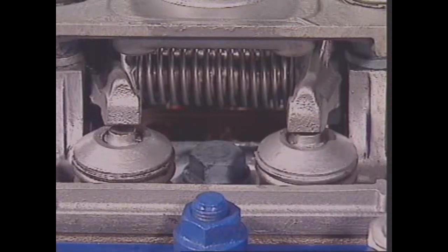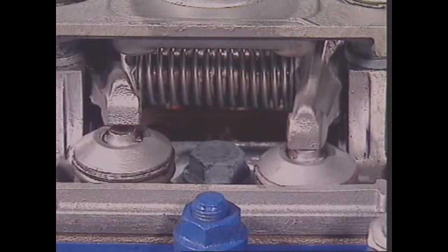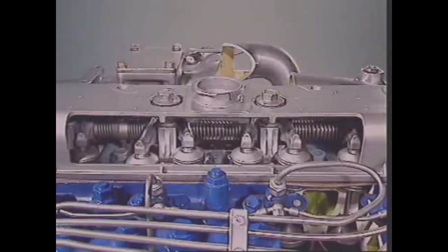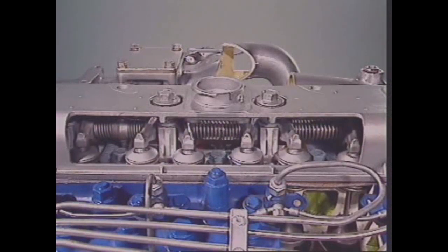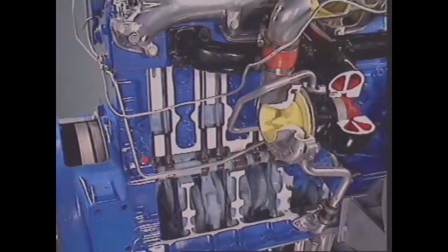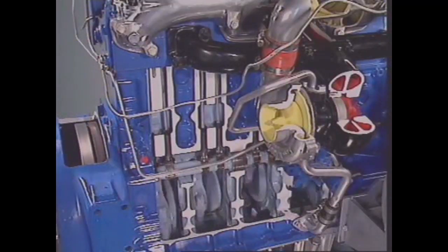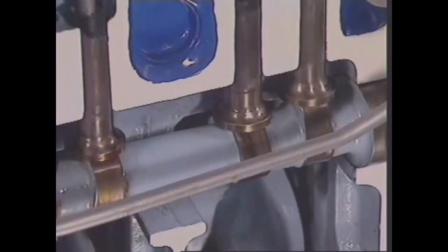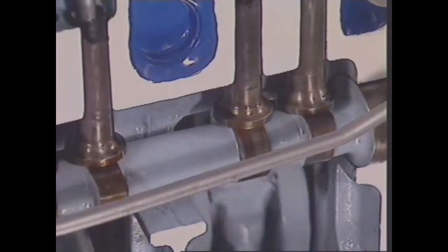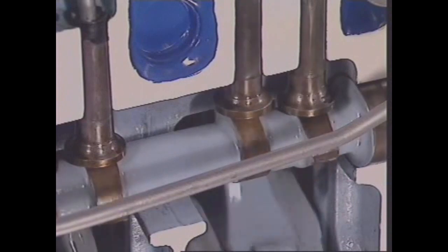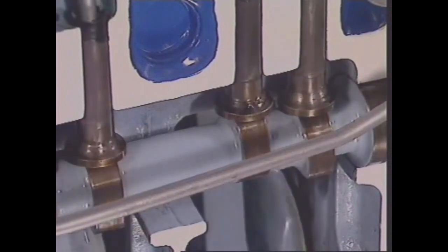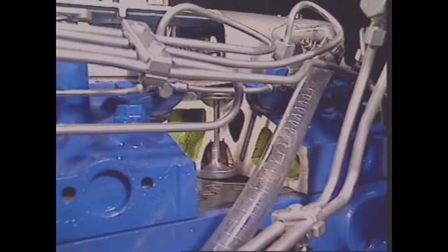The valve is held in place by a valve guide with a spring on its stem. A rocker arm compresses and releases the valve spring so that the valve opens and closes. They don't operate at random. They need a system to control them. Part of that system is the cam. A cam is a lobe on a shaft. It's specially shaped to open the valve, hold it open and let it close. So the cams control the valve action.